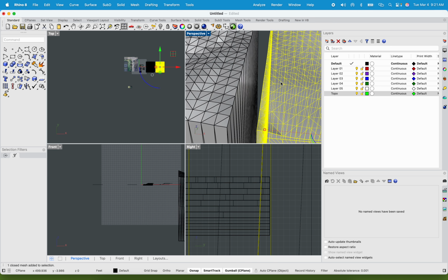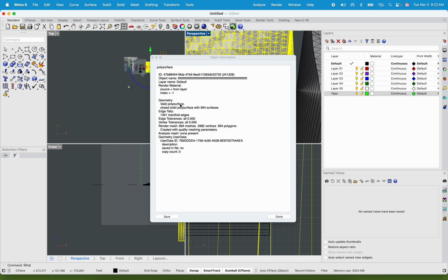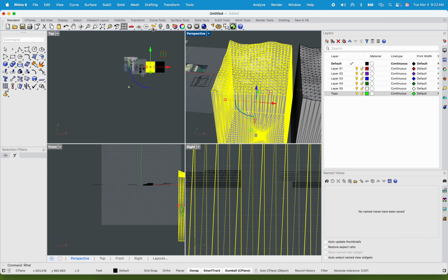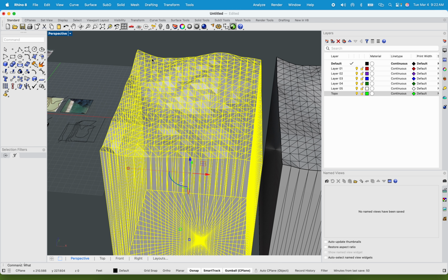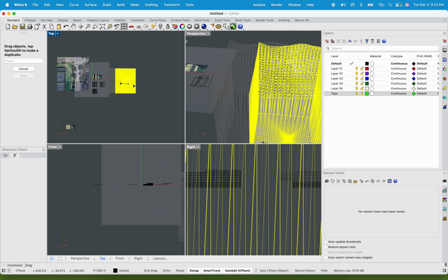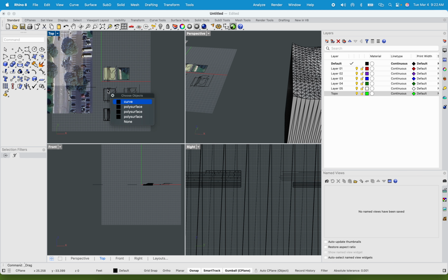And if I type in what, there's the valid mesh. And you'll see that there's a slight difference between these. Right? If I type in what, it's a valid poly surface. Poly surfaces are things that we can wire cut. So let's get an easier portion to work with here. And in my case, let's delete the mesh and just work with the surface. I already have a 48 by 48.